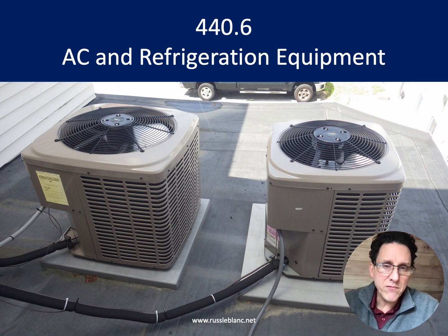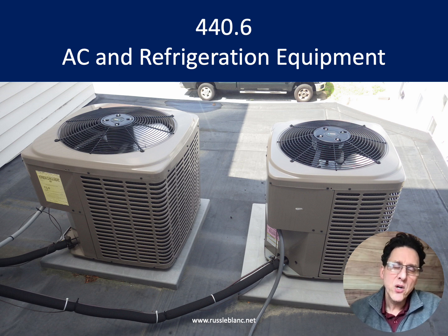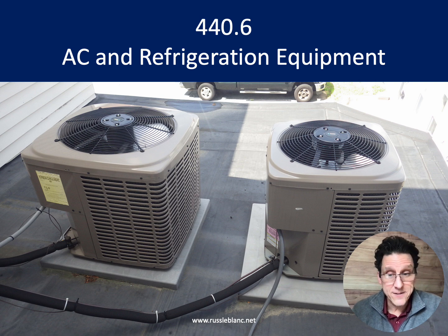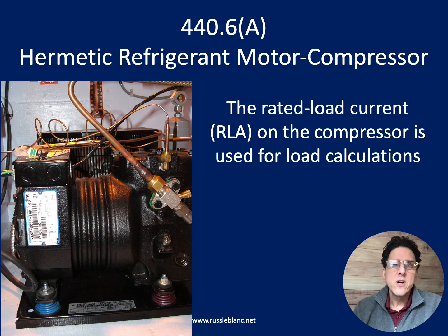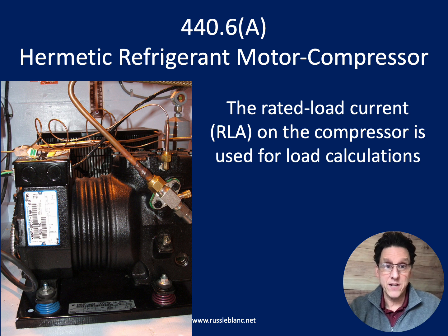Okay, when it comes to hermetic refrigerant motor compressors and air conditioning, we're supposed to look at 440.6. All right, if we go there, 440.6(A) talks about hermetic refrigerant motor compressors, like the one you see on the screen there, where it's all by itself. It's not really part of an appliance, for example. So if we are running a branch circuit to this, we're supposed to use what's called the rated load amperage instead of FLA, like a motor. Compressors use RLA, or rated load amperage. So we have to find the nameplate on the compressor and use that for the load calculation.